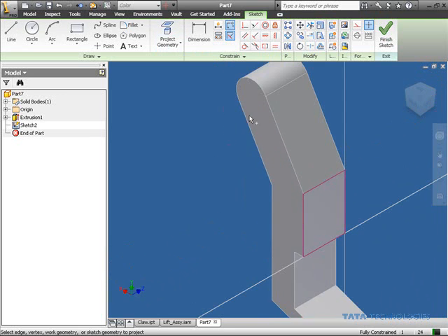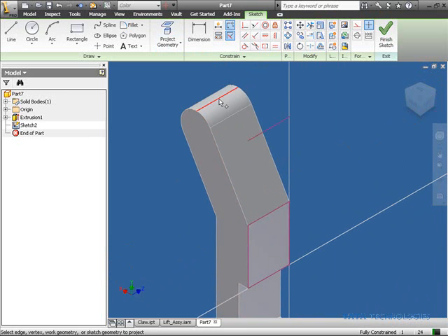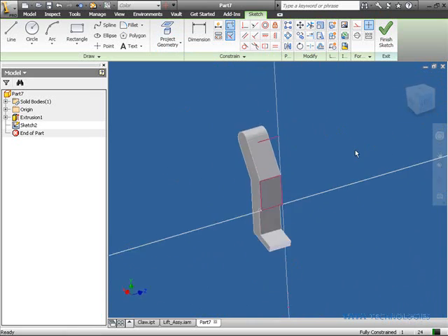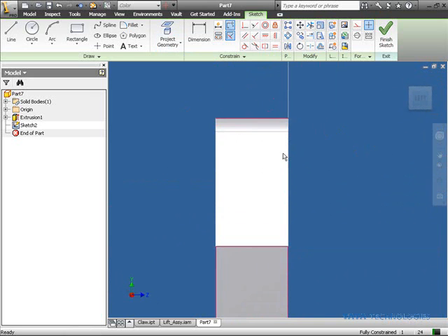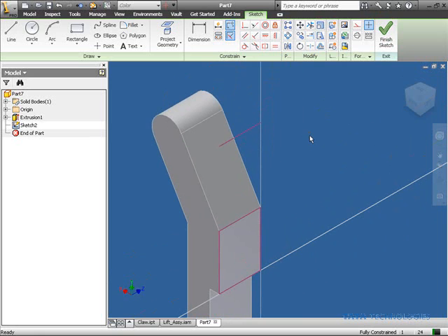and now that quadrant is projected to my sketch plane, which you will see right here when I go to my left view. That purple line is now your projected line, and I can constrain to that with any features. So I will start with a rectangle, select my projected line because it's going to constrain right to that line, and just draw freely down.